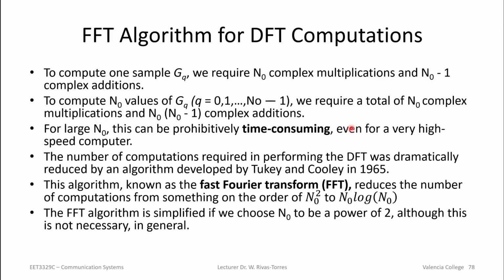Now, the FFT. So how do we do these discrete Fourier transforms, again, on the computer, on our embedded system? If we were to just do the DFT, which we can because there's expressions for it, and we know how to pick up samples from signals, and the spectrum is no different, we can pick up samples from that. But depending on what N0 is, and depending on your frequency resolution, this can be fairly time consuming, even on a computer.